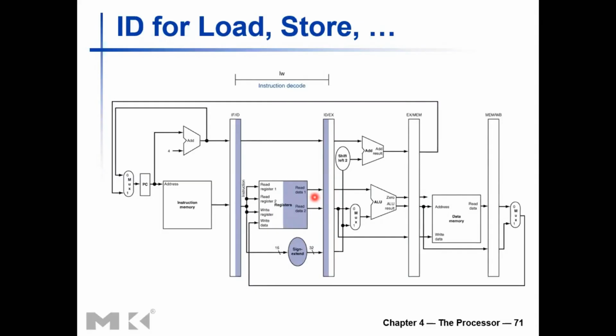So, right, what else happens in this stage? Instruction decode. The control signals are also generated in this stage, right? You look at the opcode, that is the most significant 6 bits of the instruction, and generate the control signals. You remember those 9 bits worth of control signals? You need to generate 10 actually if you need to go for jumps as well.